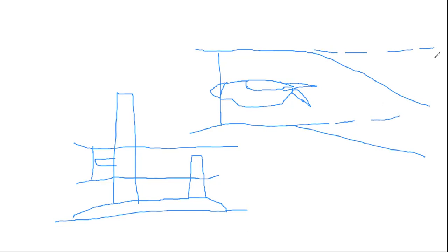And for example, when you have the tail surface in this part, in the first setting the slipstream influences the tail, but in the second setting, when the flap is down, the slipstream goes highly behind the tail. This is the difference. So it's very important to test engine influence at different flap settings. Also, it's very important to test different sideslip angles when there is an engine out case.